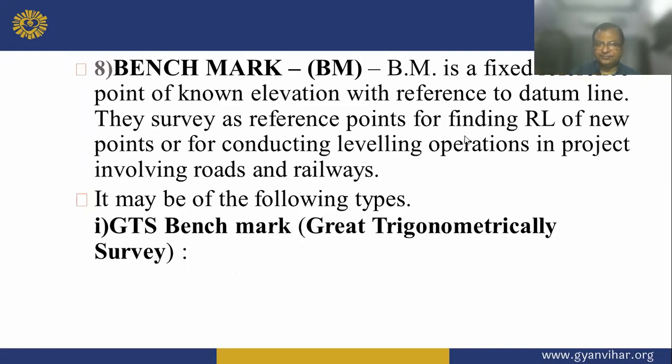Now benchmark. A benchmark is a fixed reference point of known elevation with reference to the datum line. The datum is the one we have established at Karachi and Mumbai. The survey uses it as a reference point for finding the RL of new points for conducting leveling operations and projects involving roads and railways. It may be of the following types.